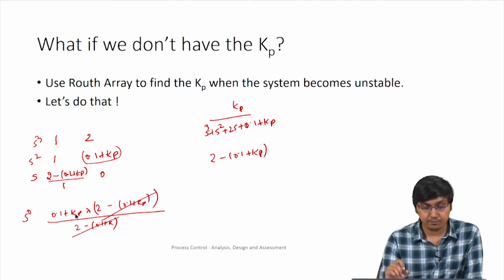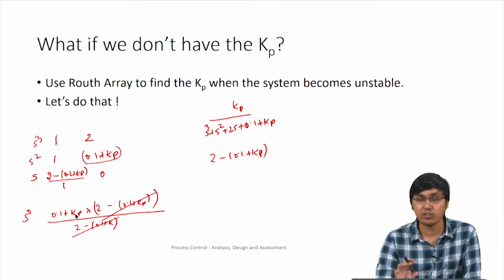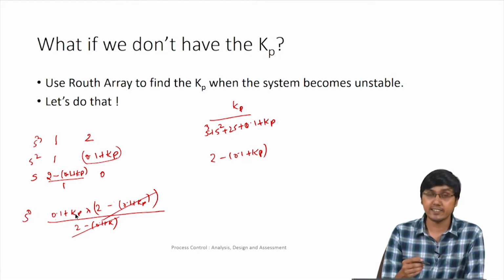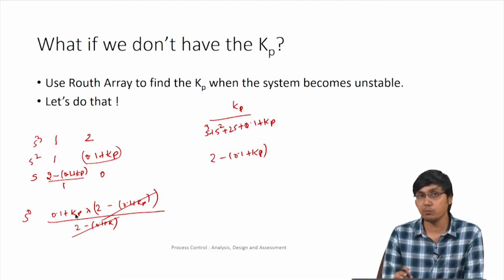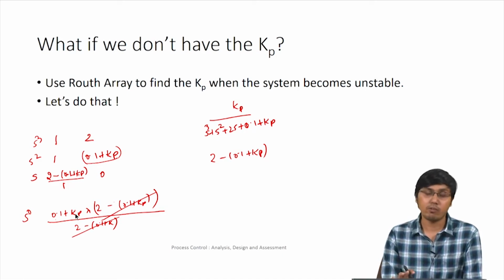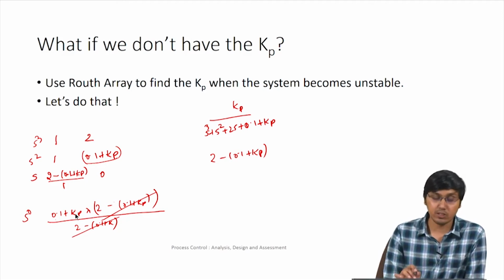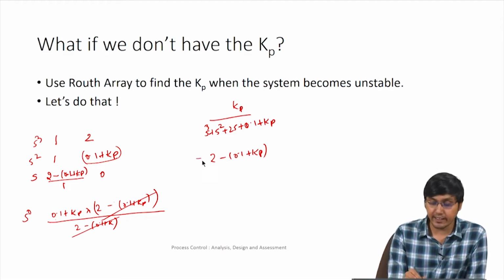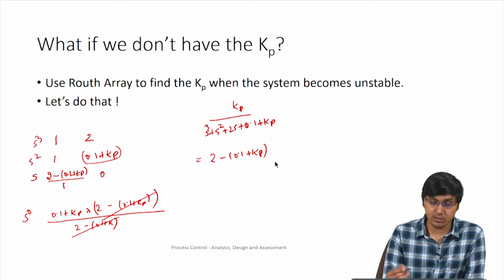And also one thing to remember is we are not trying to put a negative gain here. Since it is a P controller, let us for now take Kp only as positive values. It is not that we cannot put Kp as a negative value, we can, but for a P controller we do not normally put Kp as a negative value. So basically we will put Kp as a positive number. So this particular term is the only term of interest. So for the system to be stable, this term has to be greater than 0, okay.